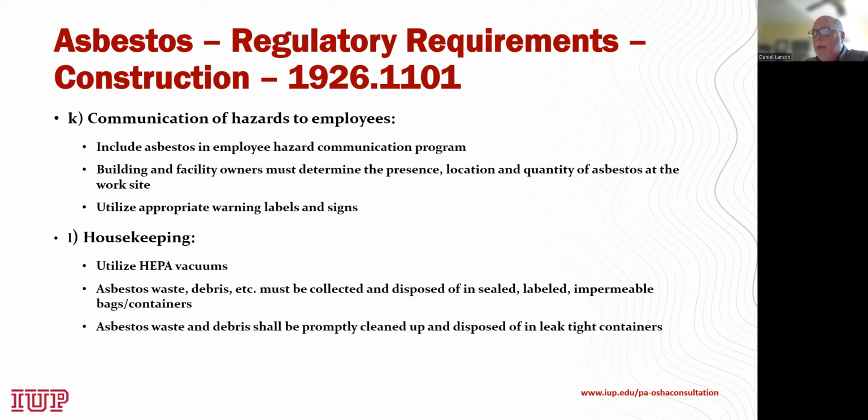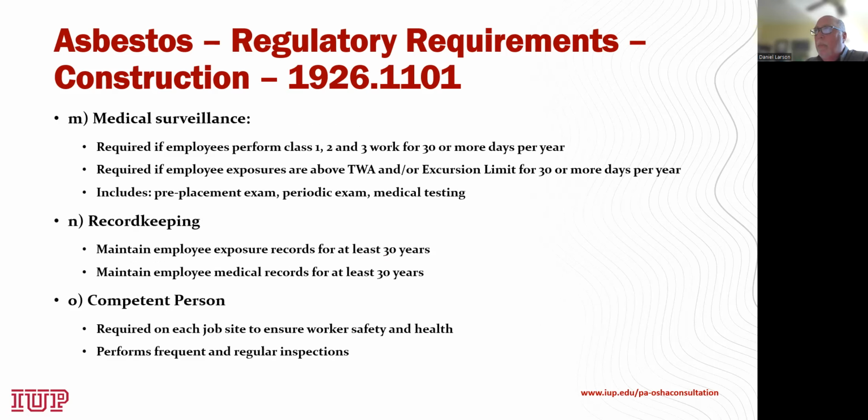Under housekeeping, you have to use HEPA vacuums. Asbestos waste debris has to be collected and disposed of in sealed, labeled, and impermeable bag containers. And any asbestos waste and debris has to be properly cleaned up and disposed of in leak-tight containers.